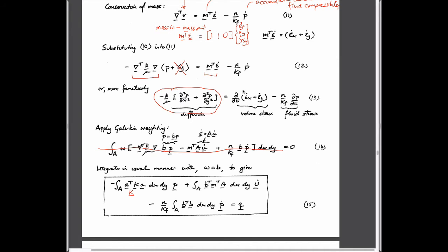Both of these terms are 0th order terms, right? So this term here is going to look something like porosity times stiffness of the fluid multiplied by B transposed B dV. And so this is going to be a capacitance term. This is also the same thing.